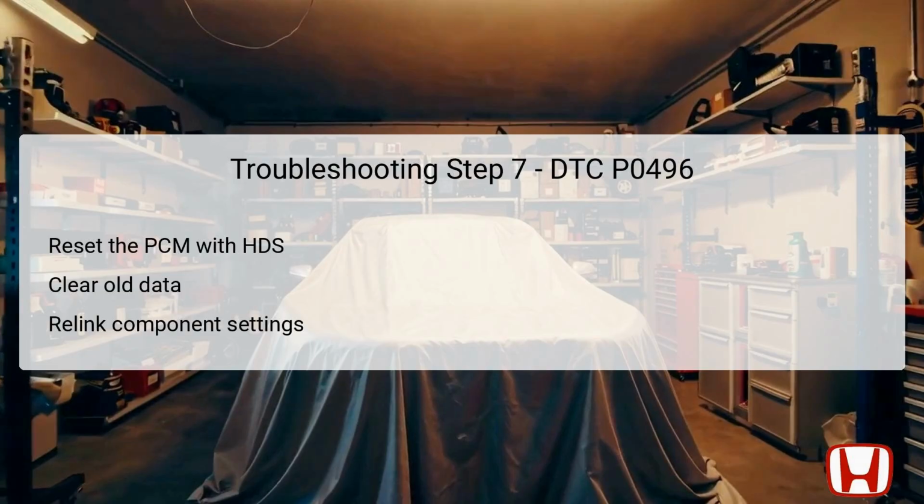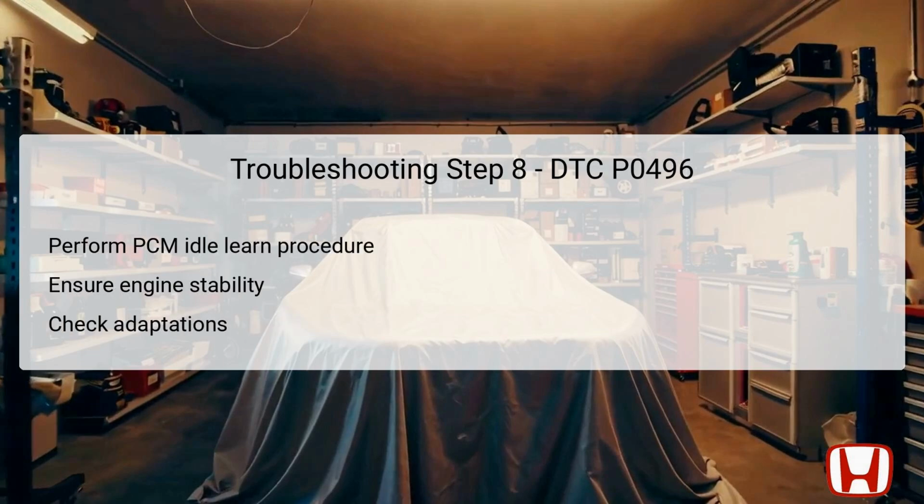The HDS guides users through this process, ensuring that all connections are properly relinked and established post-repair. Essentially, this step refreshes the vehicle's diagnostic memory, allowing it to operate optimally. Once the PCM has been reset, it is essential to perform the PCM idle learn procedure.